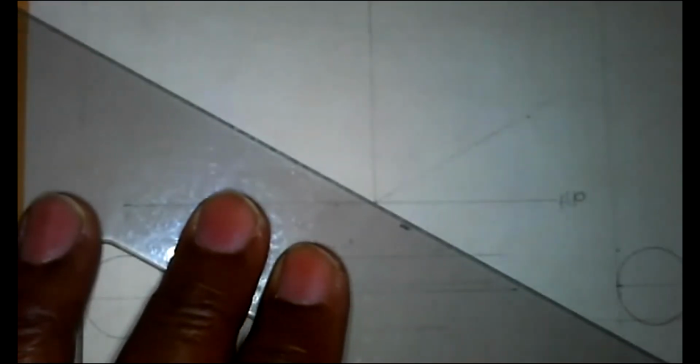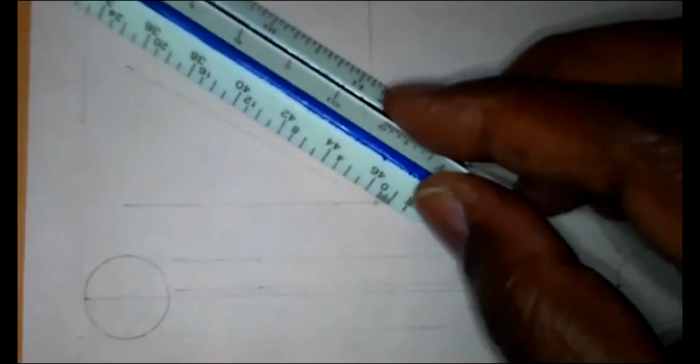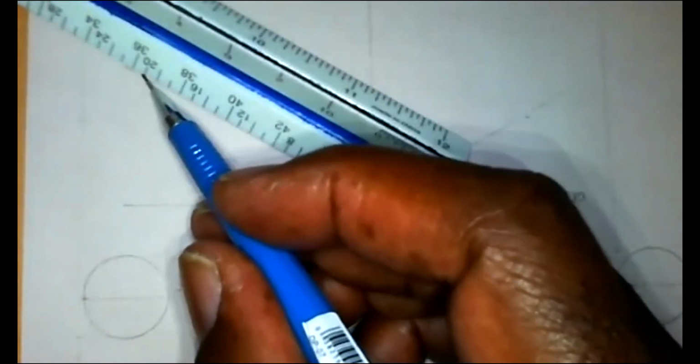So now along the y-axis, let's get that line in at 30 degrees. I'm just showing you how you're going to start. And of course, the position of this z-axis is going to be relative to the building type that you chose. All right, so along this y-axis, it was 20 feet at 1/8 of an inch. Good. So I'm going to go 20 feet. Good. So my building would end right there.